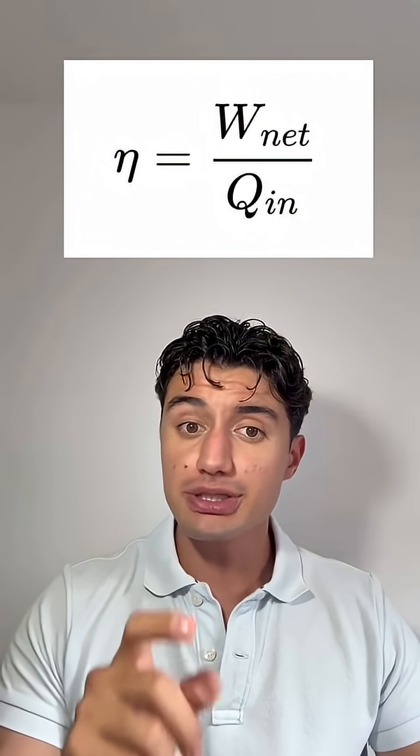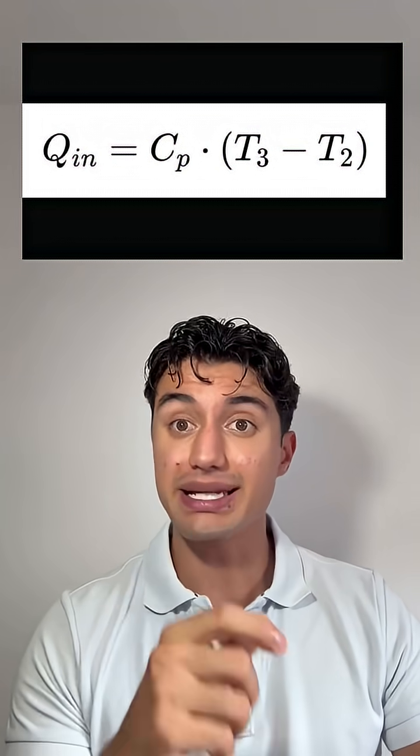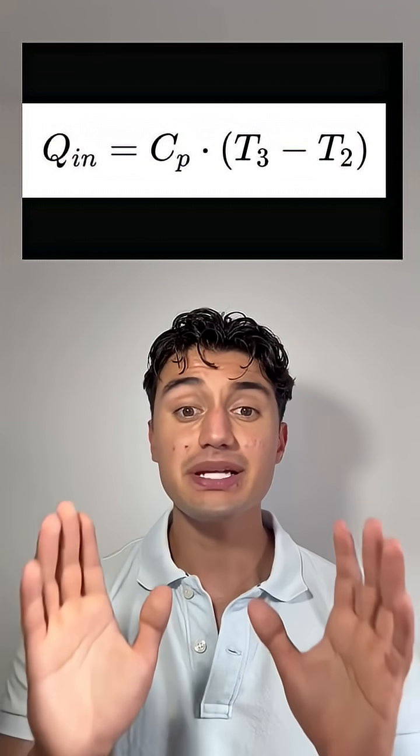We can measure the efficiency of a gas turbine with this first equation, where Wnet is the net work and Qin is the heat input. The heat input itself can be calculated with this second equation, which means subtracting the compressor outlet temperature from the turbine inlet temperature and multiplying by the specific heat at constant pressure. This basically shows us how much energy we got out compared to the energy we put in.